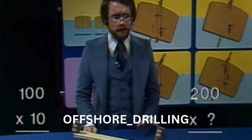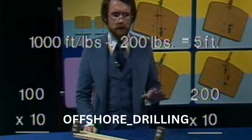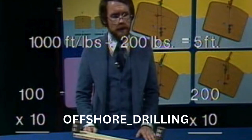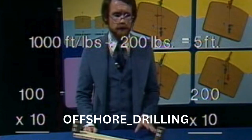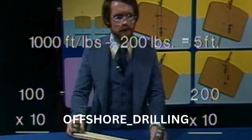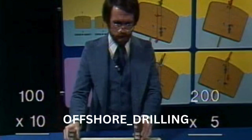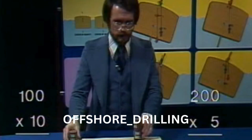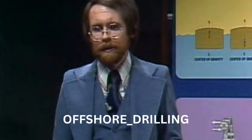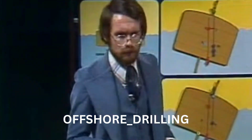So to find out the distance that we need to move the 200-pound weight from the fulcrum, we will simply divide 1,000 foot-pounds by 200 pounds of weight to get 5 feet. So we move the 200-pound weight 5 feet from the fulcrum, and the seesaw balances. A variation of the seesaw problem is a situation where we have a movable fulcrum, G, and fixed weights.